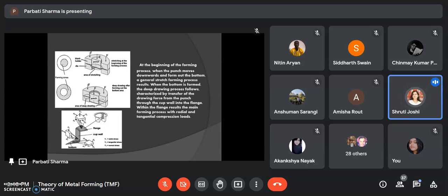For this forming, single action presses are equipped with die cushions and blank holders. The blank is held against the rubber pad by a blank holder, through which a punch is acting as in conventional deep drawing. It is a double-acting apparatus. At first, the ram slides down, then the blank holder moves. This feature allows it to perform deep drawing of 30 to 40% of the transverse dimension.